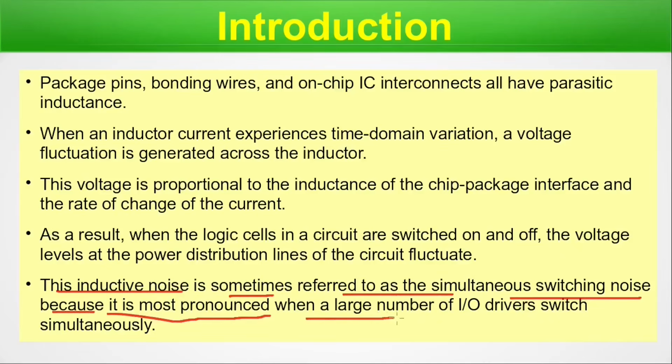This inductive noise is sometimes referred to as simultaneous switching noise, because it is most pronounced when a large number of I/O drivers switch simultaneously. Now we are talking about the chip packaging where the I/Os are, and the inductance comes from that point, and we coin a term called simultaneous switching. It is nothing but the inductive noise. The I/O pads or connection wires exist there, and those wire interconnects also contribute.